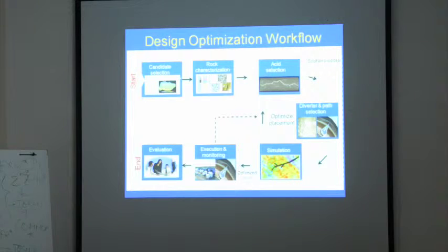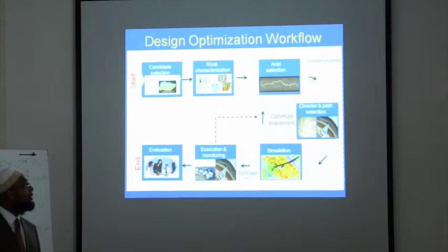After that, we have a rock characterization part in which we identify what kind of rock type you have. The mineralogy is dolomite, limestone, is it a grainstone, is it a vuggy, is it fractured, etc., right? Temperature. Once we have these two variables in, I can go to a database, select the acid, right? Which acid is going to be the most efficient for this kind of mineralogy. After the acid selection, I pick up a diverter. Depending on the completion type I have, the permeability contrast, I pick up a diverter.